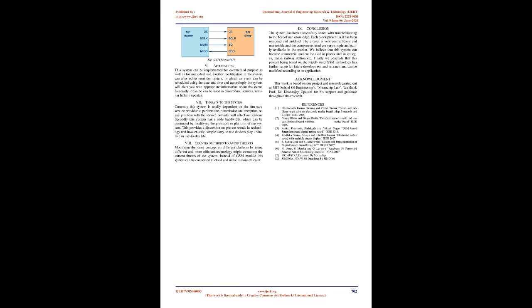SPI is a synchronous protocol based on the master-slave communication type. The master device, usually a microcontroller, controls the slave devices, because the slave device takes instructions from the master device. It allows transmission of data from a master device to one or more slave devices and from slave devices to master devices over short distances at high speeds, in megahertz.